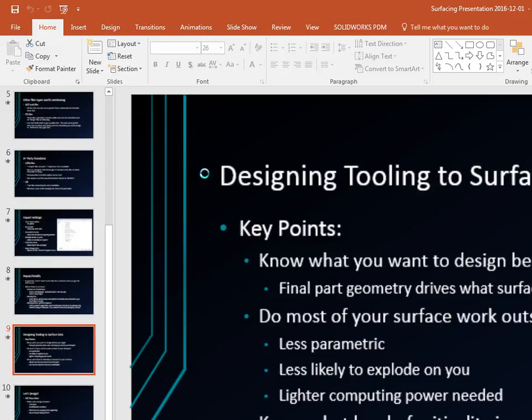Like this I would probably just untrim these edges here to get that guy, and then you can just untrim that, and then you want to merge with original too. If you don't take merge with original, it just makes a new face there, and then you got this weird double face thing going on.